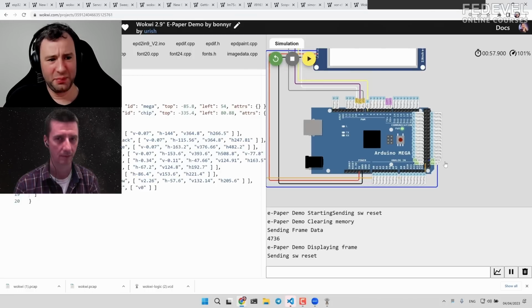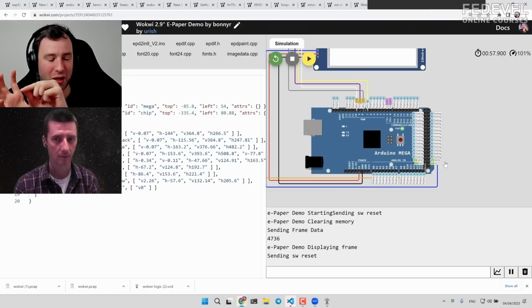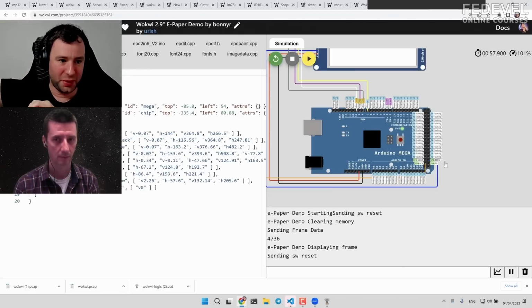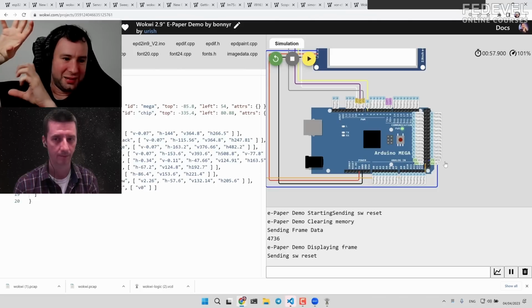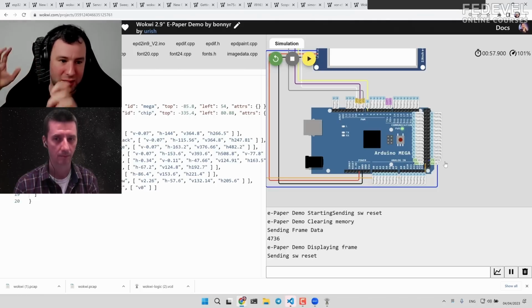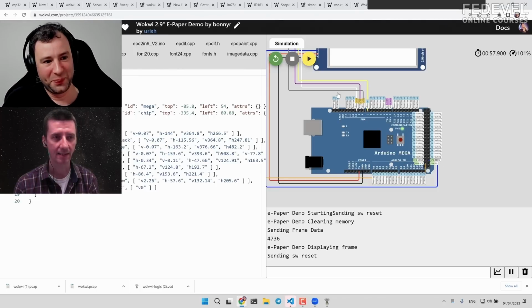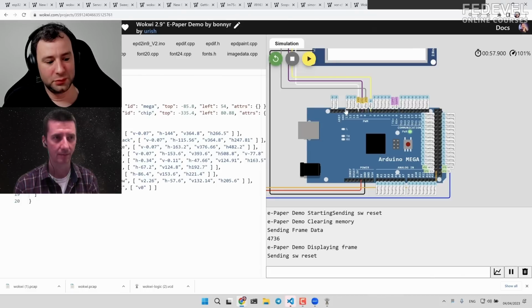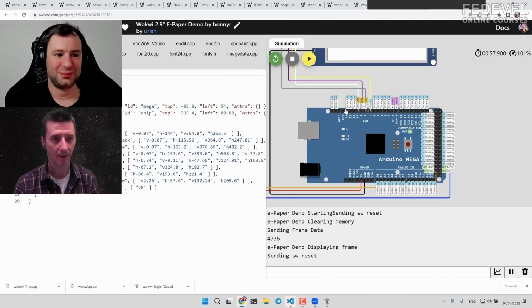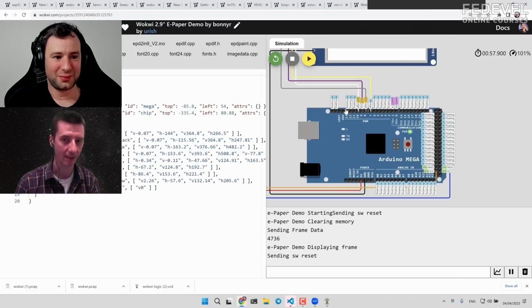With boards like the Mega, the peripherals are pretty constant, they don't move around pins. But on the Pico, we just had an example today where somebody sent me a project that didn't work because the peripheral was coming out on different pins. It used the SPI on different pins than he thought, so we wired it incorrectly. So you could immediately see that the peripheral is connected to a wrong pin, or the pin is not configured properly for the feature which should be there.